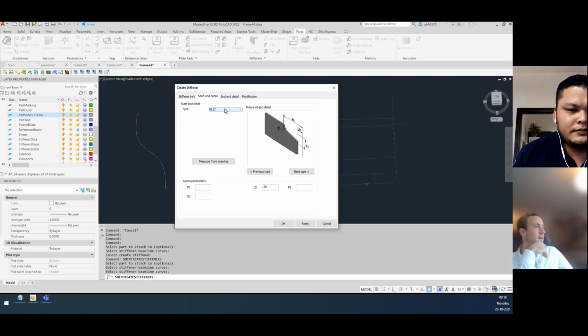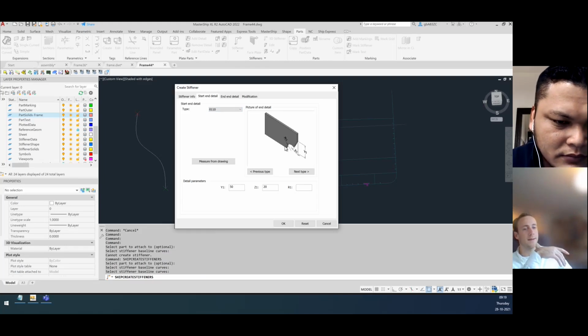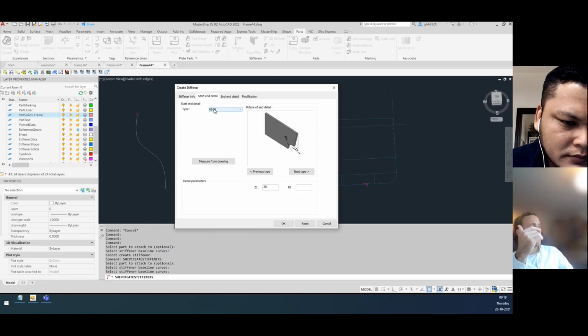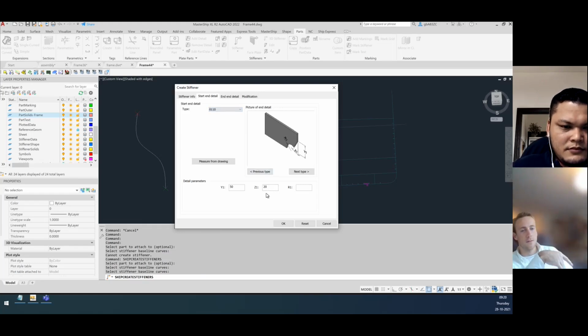But this flat bar has a bit of a strange end detail. So maybe, yeah, well, this is strange enough. So, for example, a welding hole is not very easy to make. So, say you order a flat bar and you want to only cut this off. That's easy. You can easily do that in the workshop. If you want to make maybe this end detail, it is harder to make in your workshops. So you might want to have this cut out, to put this in your nesting.